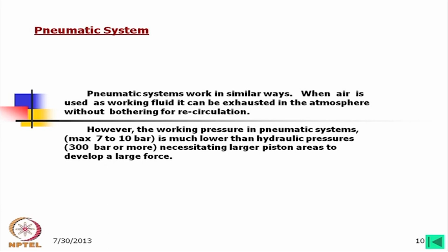So, if we think in this way, we will find that pneumatics under the fluid power banner has separate applications from hydraulics under the fluid power banner. Normally, hydraulics are used to transmit very high power, and pneumatics are used for small actuation and control.